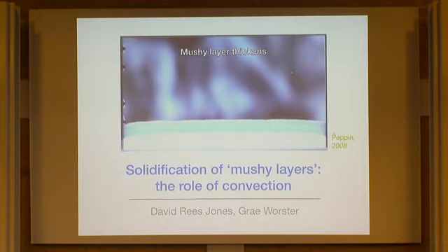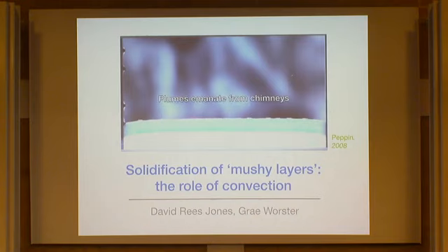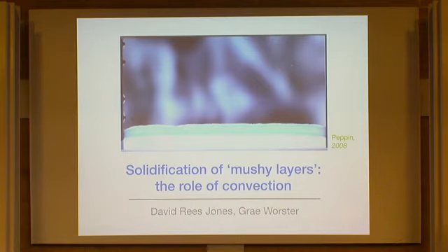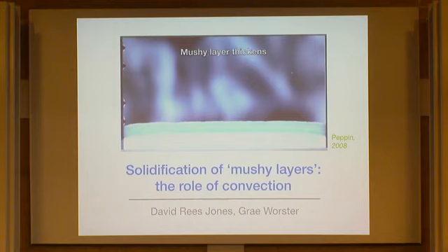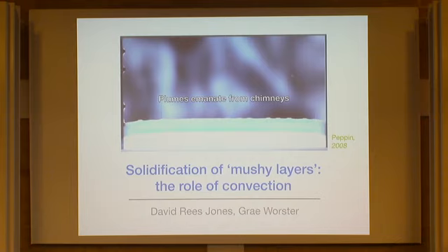And what I want you to focus on is the production of these plumes from liquid regions inside the mushy layer. This is caused by an internal process of convection, which happens inside the mushy layer, and it's one of the main ways in which these systems segregate, leading to macroscopic segregation, where the bulk composition of this region changes over the course of the experiment, and microscopic segregation. If this experiment were suddenly to be stopped, you would see this structure frozen into the solid.